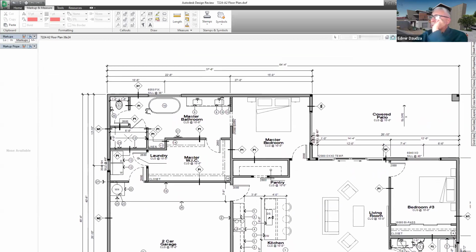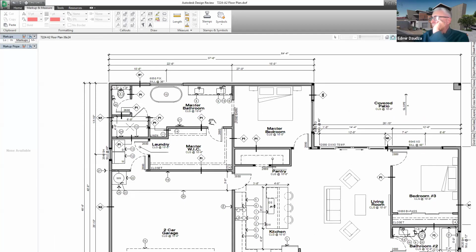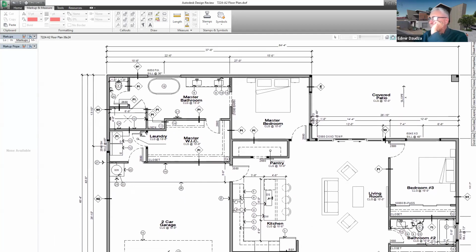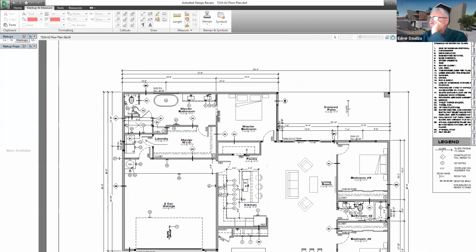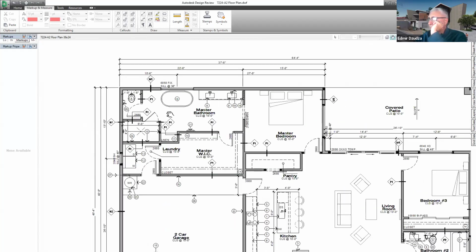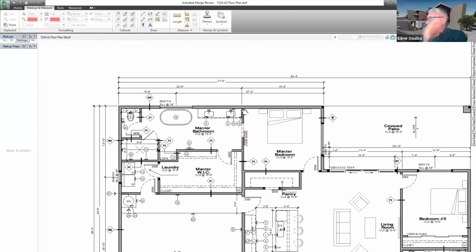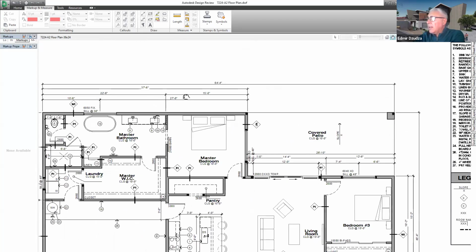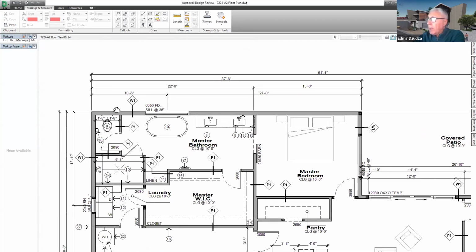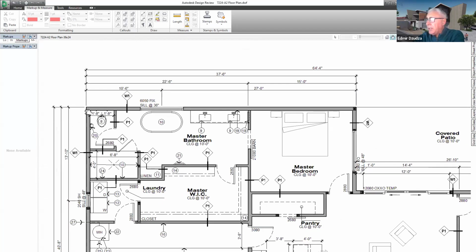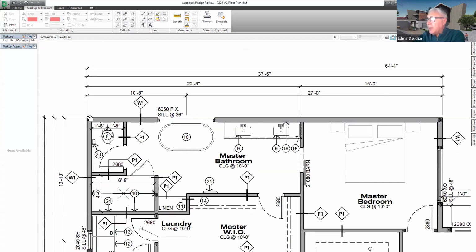So when we're doing the dimensioning, we have to put ourselves in the shoes of the people on the field, people who will be building this. So let's say, if I start from here, it is important that all dimensions start from the exterior, and then we go on.